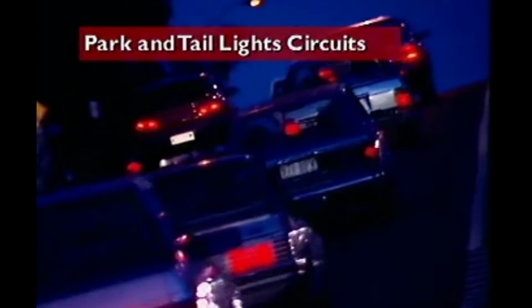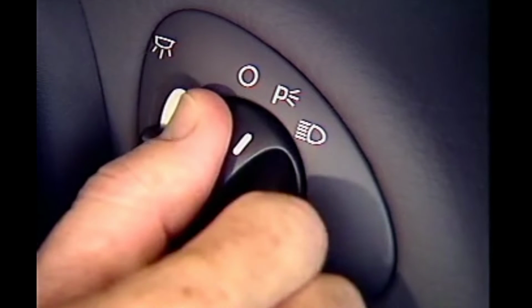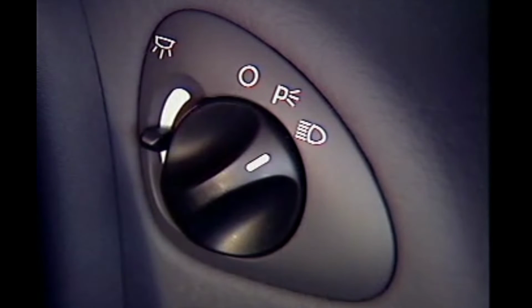This section examines parking and tail light circuits. For motor vehicles and trailers, 2 red tail lamps operate when the headlight switch is in the park position and the headlight position. The 2 lights are located close to the widest points of the vehicle, so that the vehicle width can be seen by other road users.